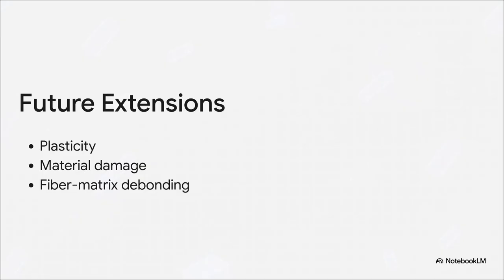Because the framework is based on finite elements at the unit cell level, it can naturally be extended in the future to include nonlinear effects like plasticity, damage, and fiber matrix debonding. Remember step 1? Because we're still using an actual 3D finite element simulation for that single unit cell building block, we aren't limited to just simple elasticity. Down the road, researchers can easily program that single matrix block to deform plastically, or program the interface between the fiber and the matrix to literally snap and debond under high stress. When you average that behavior out, you get incredibly rich, complex, real-world material failure predictions.